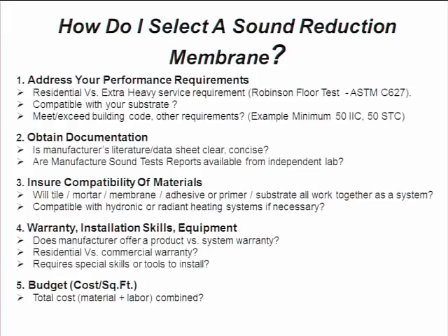And the other side would be from the installation perspective, when you're looking at cost, does it require anything unique or anything different in reference to the skill level of the installer, as that will drive up the labor cost. The final thing would be to look at the cost per square foot of both the material and the labor. Some of the membranes have excellent soundproofing, but the cost of them is driven up in reference to the labor cost to install them.